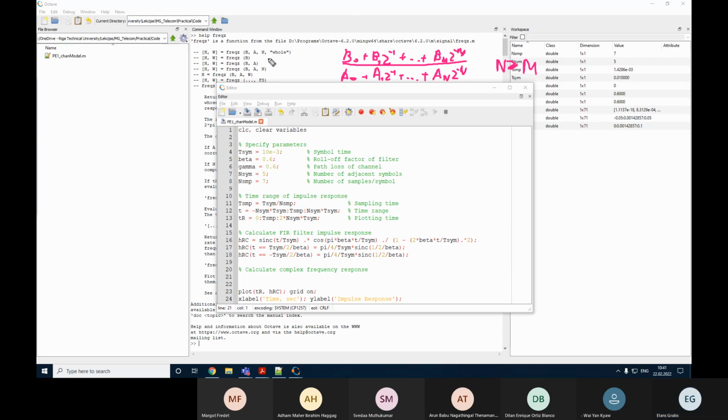Now, we have vector b consisting of the elements b0, b1, and so forth up to bm. We have vector a consisting of similar coefficients without these z values. Yes, so in MATLAB we only specify these values, these variables before the function variable z. Yes, so these are vectors. Here we have commas, and here we have 1, and an. We put them in here. We specify the range of frequencies where we want to calculate, and as a result, we get this frequency response. So let's do it.